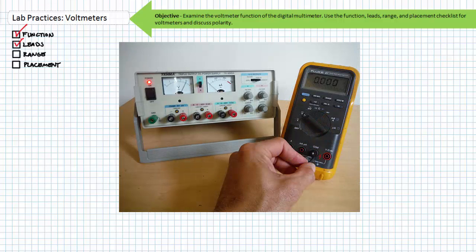Leads. Now that the DC voltmeter function is set, figure out where the leads go. The black lead goes into the black common hole. This is the lead that will be used as our reference.